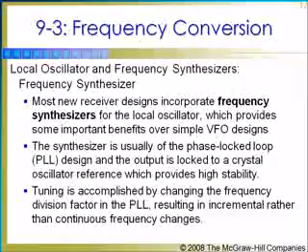Tuning is accomplished by changing the frequency division factor in the PLL, resulting in incremental rather than continuous frequency changes. The former disadvantages of frequency synthesizers, higher cost and greater circuit complexity, have been offset by the availability of low-cost PLL synthesizer ICs, which make local oscillator design simple and cheap.